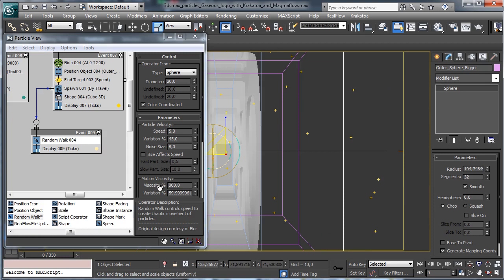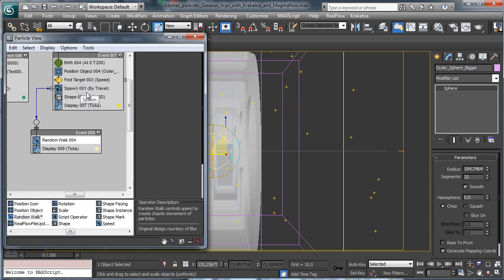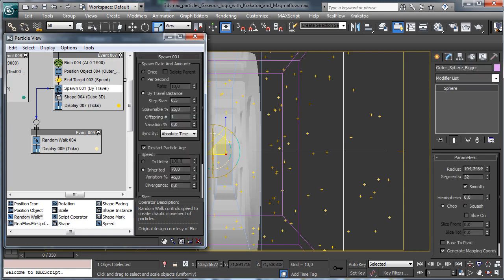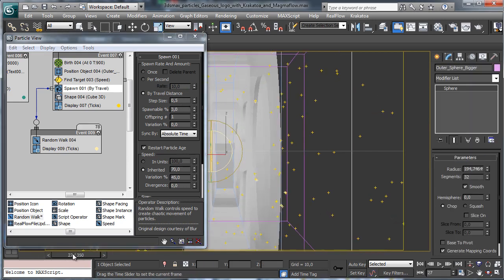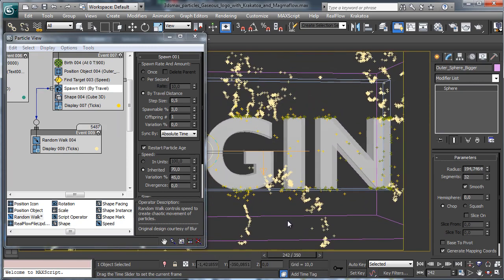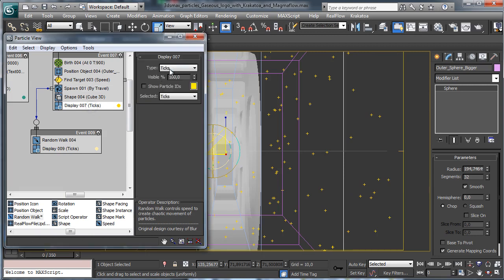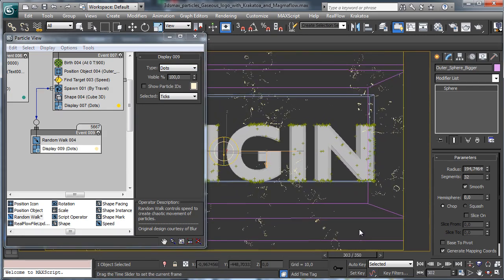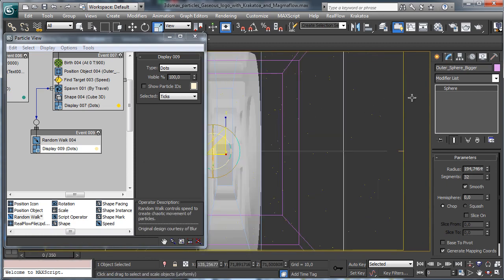All these particles can have a little bit of dragging, so I'd like to say that they are moving slow. So first of all, let's have more particles, let's say maybe 900. But we say that just a lower percentage will have the spawning, let's say maybe 3%. So actually we have something like that. Okay. And let's have dots there also. So we have just some points, and then you see that we are creating some filaments inside the scene. Nice.